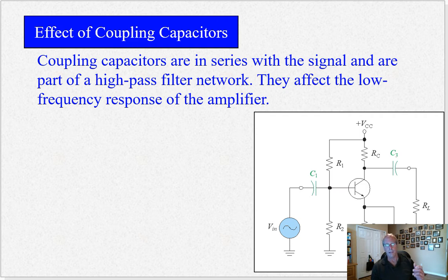Now, the resistors are pretty clear. For example, in this common emitter circuit, the resistors are shown here: the bias resistors, collector resistor, and the emitter resistor. The capacitors are coupling capacitors on the output and on the input, and of course this bypass capacitor down here on the emitter, which improves the high frequency response because it shorts it out. C2 in this case is shorted out in high frequency conditions, which increases the collector-emitter current in this amplifier.